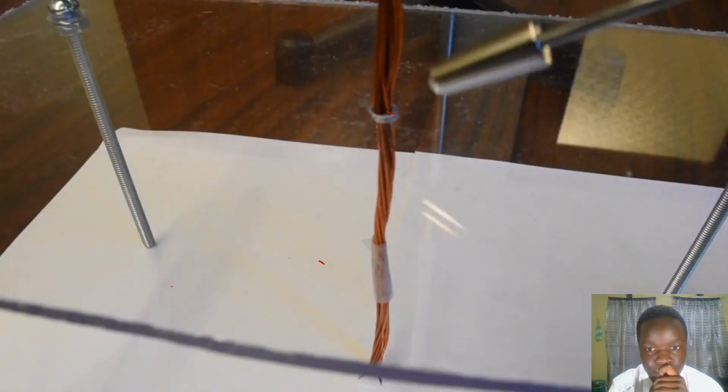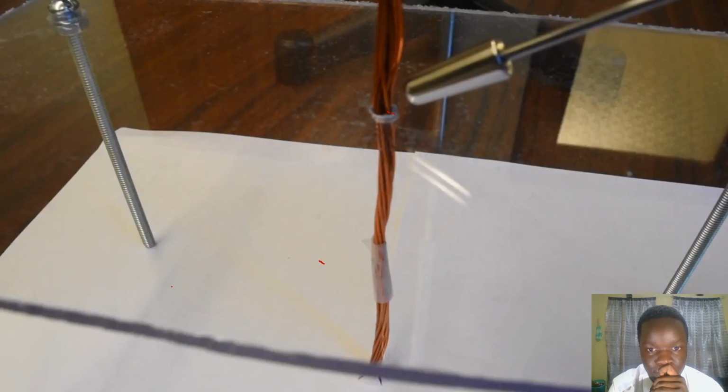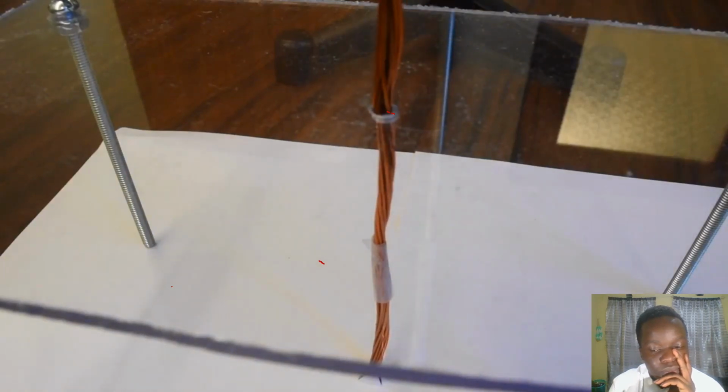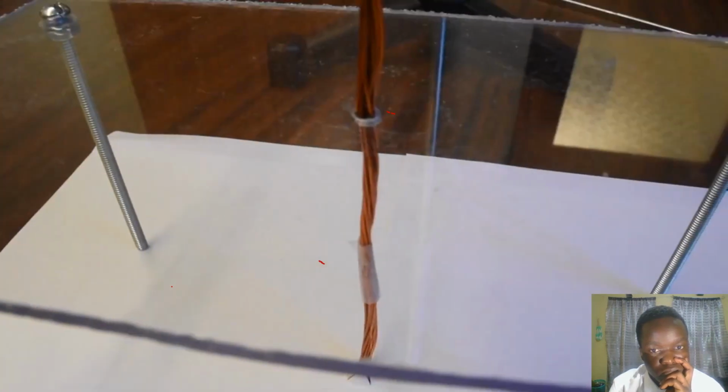I have a piece of plastic through which I've drilled a hole, and then I took a wire and looped it through the hole 10 times. So I have 10 strands of the wire flowing through this hole. If I have 1 amp of current flowing in the wire, I will have essentially 10 amps flowing in a straight line through the hole in the plastic.